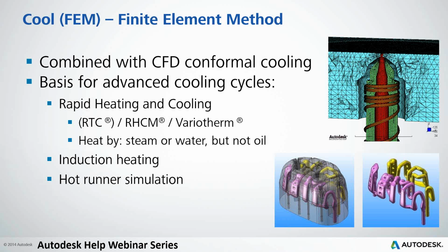Okay, but the finite element method is also the basis for what we could call advanced cooling cycles. First, we could combine this methodology with CFD conformal cooling. So you know that nowadays, with additive manufacturing, it's possible to create very complex cooling scenarios or cooling channels. And these cooling channels could not be modeled by beams. Here is where we could combine the CFD technology with the finite element method in Moldflow.